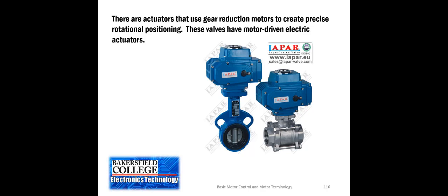As that disc gets more in parallel with the flow of liquid, as it opens more, then we'll get more flow through that valve. So rather than taking a valve and having to manually turn a wheel or rotate a knob, these electric valves do that with electricity into a motor that's then gear reduced, and it opens or closes the valve.